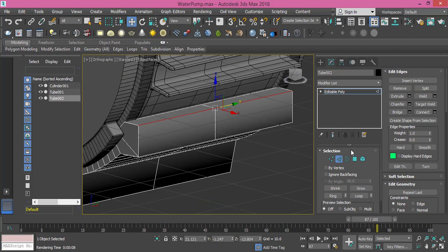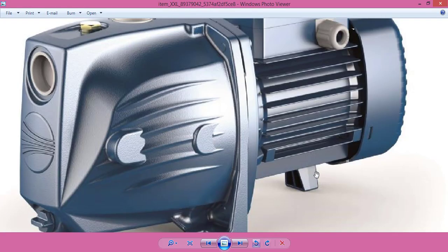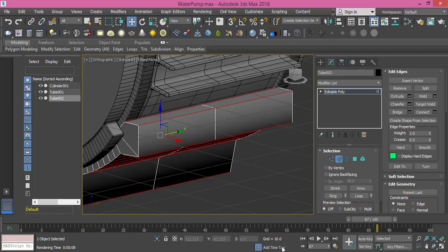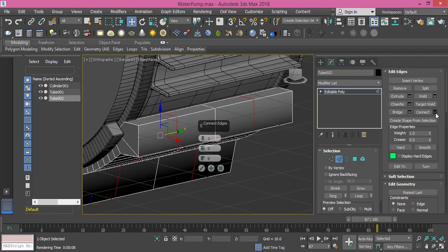Select this and then make ring, and let's connect. I need to make two edges here and here to create these two pieces, and then I will make extrude inner in the middle. So I use connect, and let me try to take them apart. Actually it doesn't work, so let me raise the number of connects to 2 and press OK.